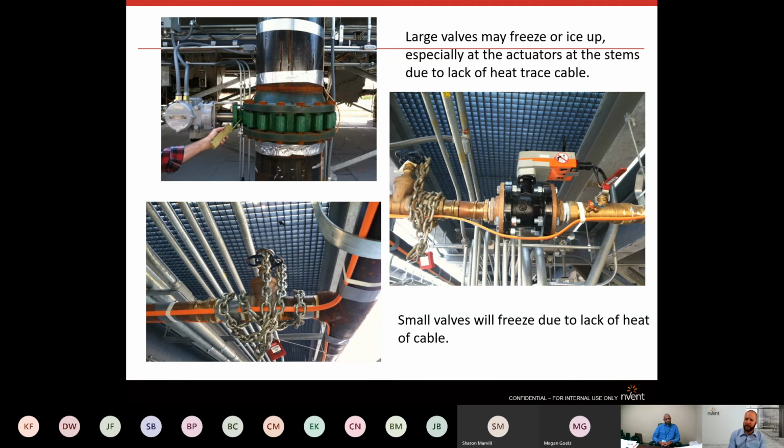I always find it surprising when you're getting involved in a project and they're really scrutinizing the cost of the heating cable per foot, and they're not paying much attention to the insulation type or thickness or optimizing that insulation system. When really, it depends on the project, but you could even say 60 to 70% in some applications of the cost of a heat tracing system is in the insulation. So that's why we like to get involved early and start hopefully influencing that system